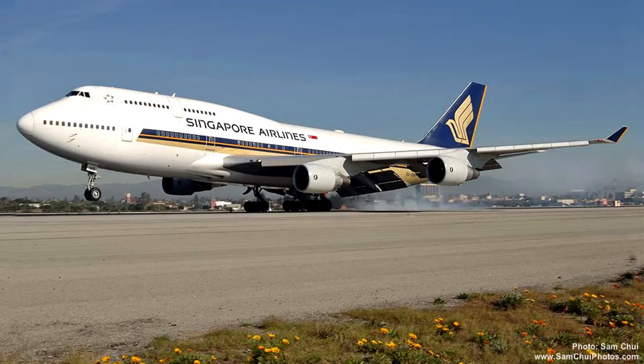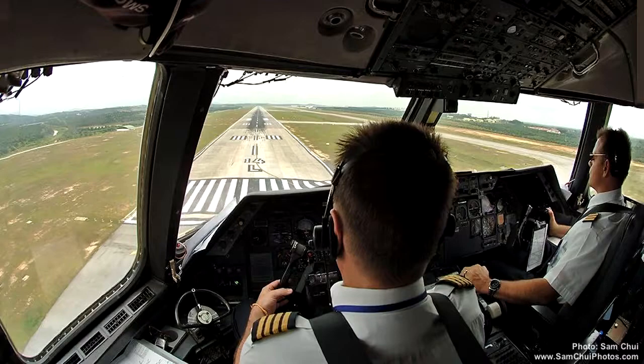If a precision approach is flown correctly, when a pilot reaches his decision height, the aircraft will be safely at the place it should be, just as if visibility was perfect. From this point in the approach, the landing will be continued to touchdown visually. This portion of the approach is not VFR, it is completing the IFR procedure visually. Except where blind landing equipment is fitted, a precision approach will lead to a visual final approach and touchdown. To accomplish this, a minimum RVR and visible runway centerline is required.